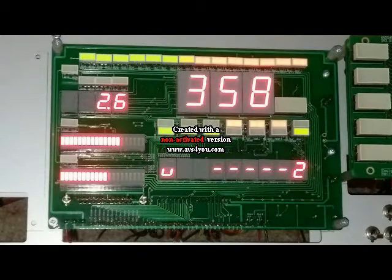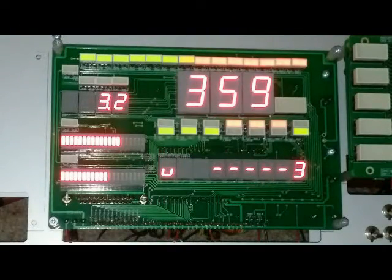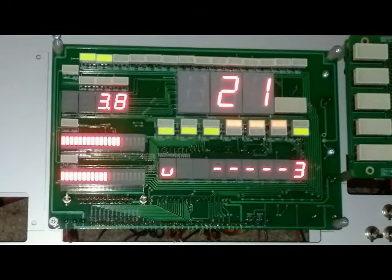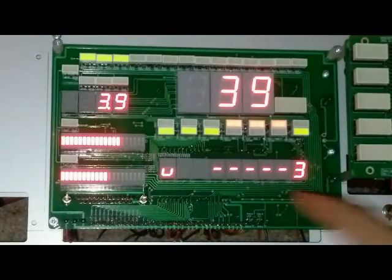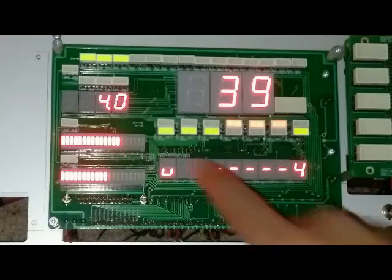So in normal running mode, we have a speedometer, which is currently receiving a simulated signal of a very high value so that we can see the trip meter clocking up. The speedometer itself is a 3-digit numeric display associated with a bar gauge display at the top. The trip meter is here, and at the bottom here we have an odometer measuring total miles. This unit's only just been programmed, so we have only 3 miles on it.